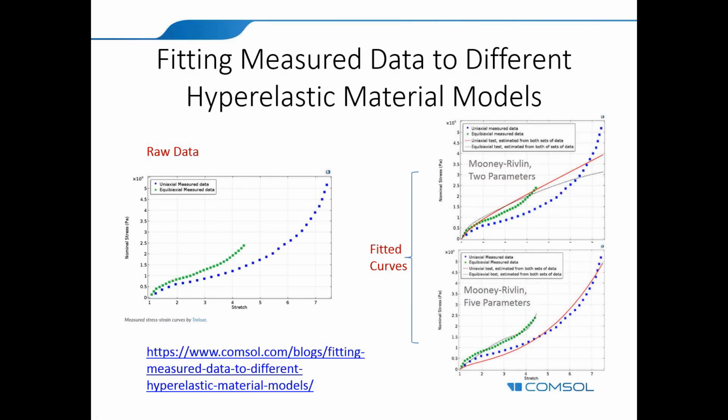Now, to get the material parameters required for hyperelastic material modeling, curve fitting is required against a number of hyperelastic material models. Now, like I mentioned earlier, it is not enough to have just uniaxial data for curve fitting because the uniaxial data does not contain information about deformation in transverse directions. And additionally, when curve fitting experimental measurements, perhaps not all data should be given equal weight. So it may be that the response in a certain strain range has a larger impact on your simulation results. And most of these things related to curve fitting, related to fitting the experimental data that you have for various tests can be done within COMSOL.